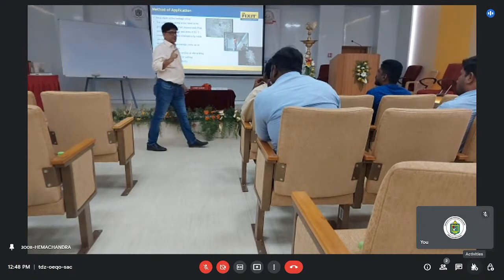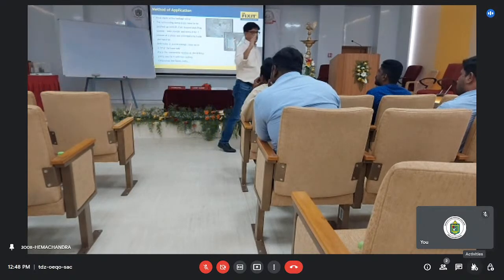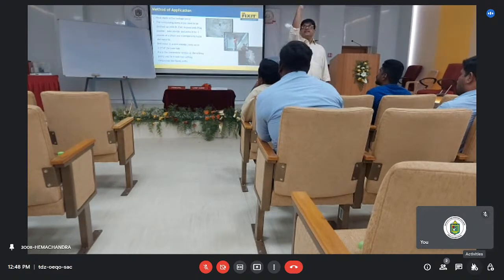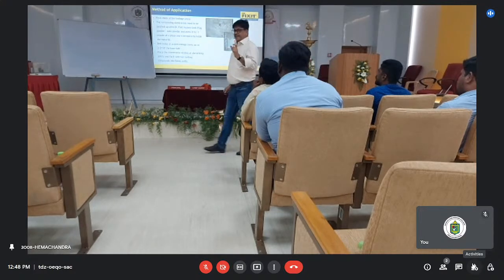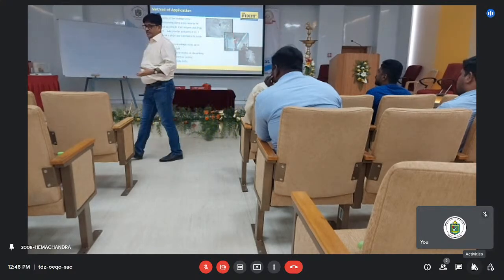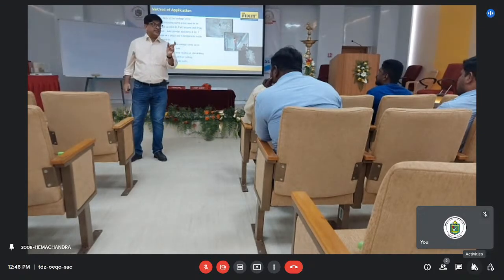Drilling holes should always be at an angle of 45 to 60 degrees. It should not be directly at 90 degrees or 0 degrees. So always at a 45 to 60 degree angle. In case of active leakages, depending on the situation, in grouting there are some principles.